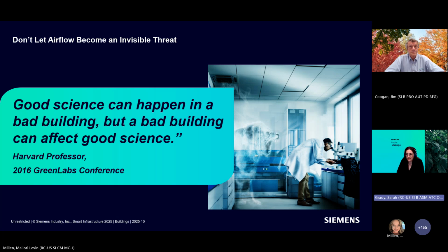Exhaust systems, if it's a plenumized exhaust system or not, that's going to make a big difference on how we treat the variability of the exhaust and fume hoods as well. If you have a bypass fume hood, there is a way that you can convert that to make it a variable volume fume hood, but it does require additional sensors and stuff. So yes, there are mechanical limitations, but they are all able to be overcome without having to tear down the building and create a whole new mechanical system.